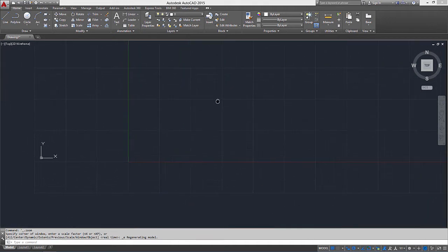And if I just press the wheel down and pan up, what I'd like to see is the user coordinate system, the UCS, sitting there in my screen. So I know that's 0, 0. So when I start drawing, then I can reference back to this. If you haven't done that and you start drawing, then parts of it might be disappearing off the screen. It doesn't matter if that happens, just carry on until you've completed the task and then double click the wheel and you will zoom to the extent.